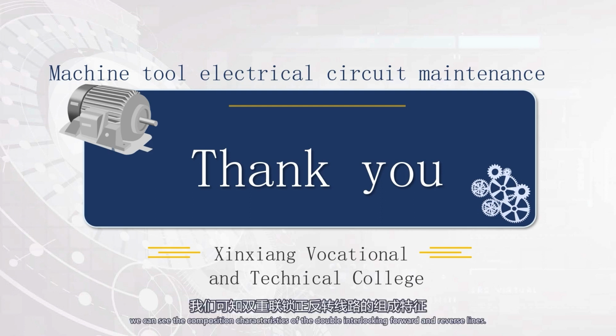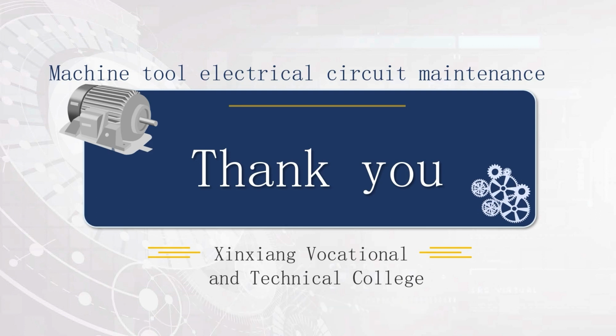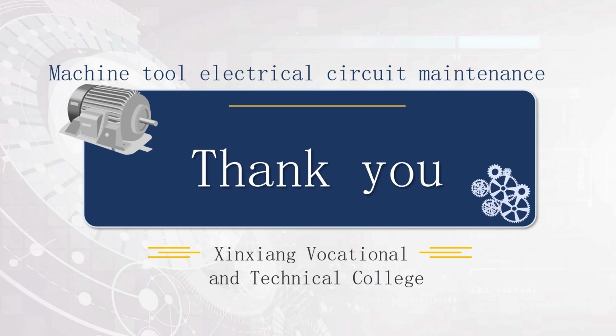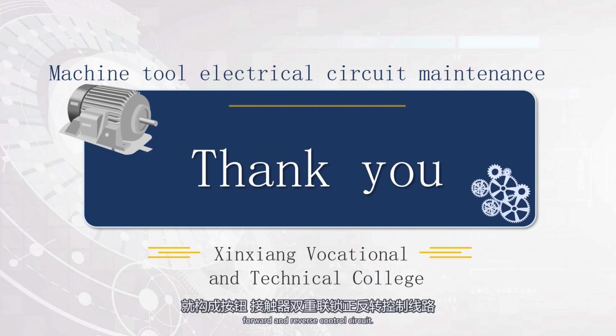From the figure, we can see the composition characteristics of the double interlocking forward and reverse lines. Which double is in the double interlocking forward and reverse circuit? One is an interlocking system consisting of a normally closed contact of an AC contactor connected in series with another coil. Another aspect is the interlocking formed by the normally closed contacts of composite buttons connected in series in the other party's circuit. The dual interlocking forward and reverse control circuit adds contactor interlocking on the basis of button interlocking, forming a button and contactor dual interlocking forward and reverse control circuit.